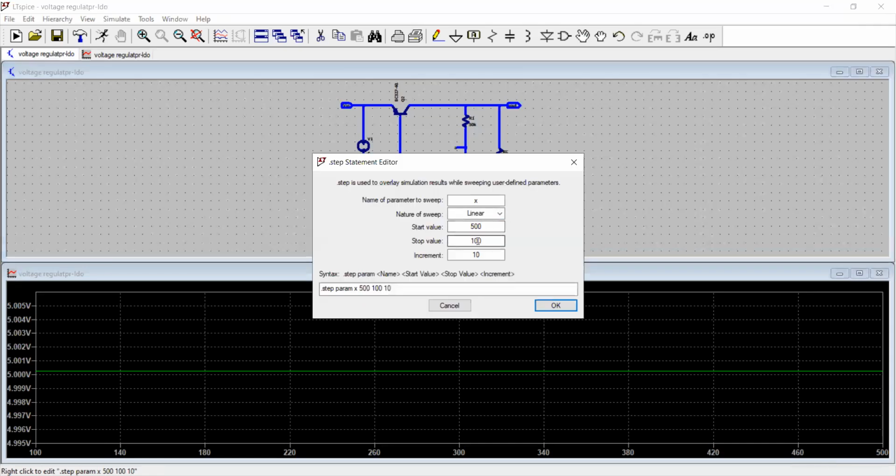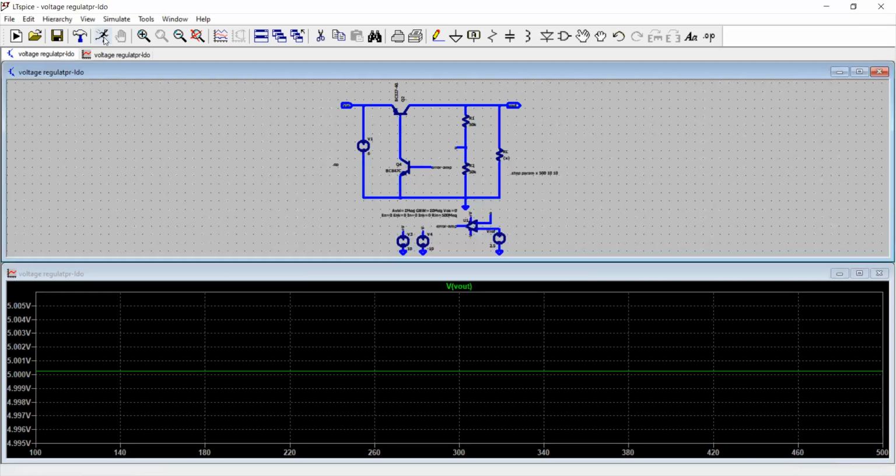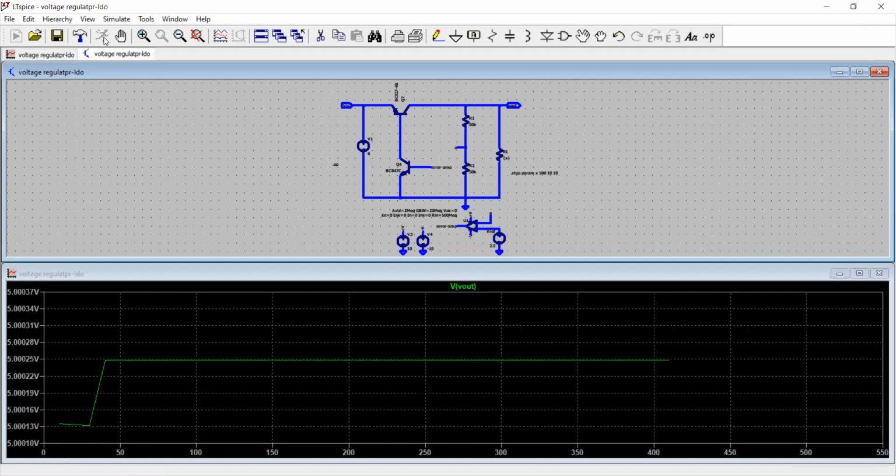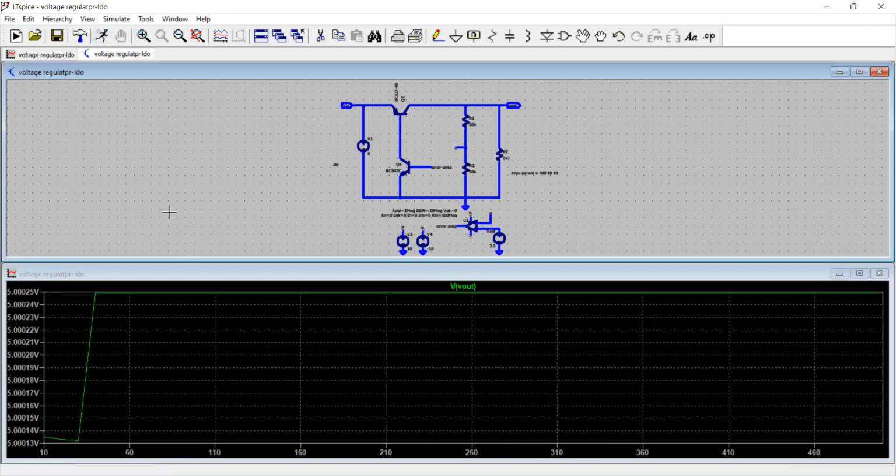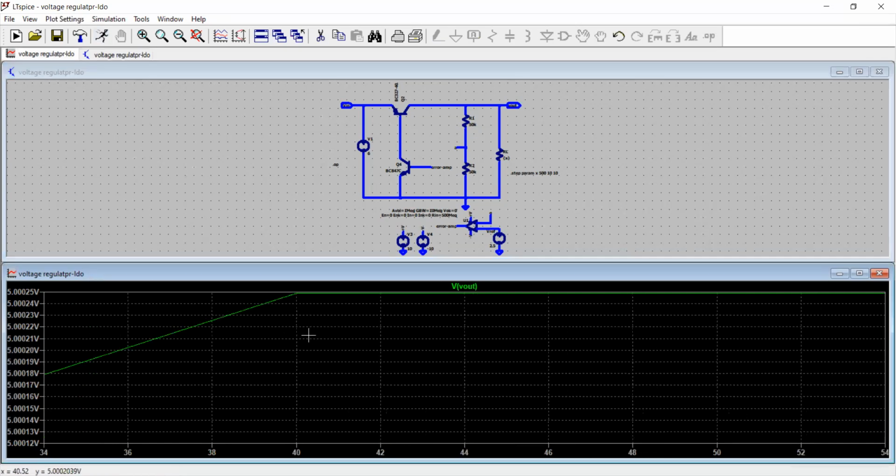Let's say I go to 10 ohm, more current, and click again. Now you have a problem. So your output is perfectly fine if you have a load resistance of 40 ohm lowest. It means 5 divided by 40 ohm is the maximum load current that your circuit can supply to the load under these conditions. 5 divided by 40.